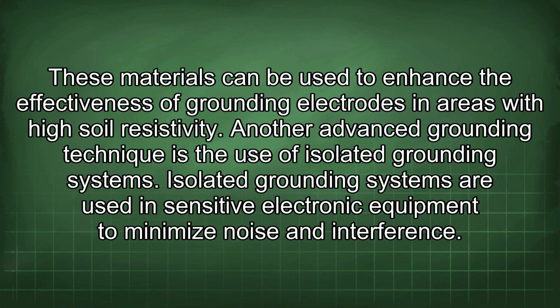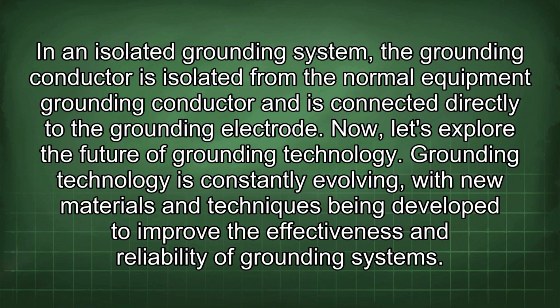Another advanced grounding technique is the use of isolated grounding systems. Isolated grounding systems are used in sensitive electronic equipment to minimize noise and interference. In an isolated grounding system, the grounding conductor is isolated from the normal equipment grounding conductor and is connected directly to the grounding electrode. Now let's explore the future of grounding technology.